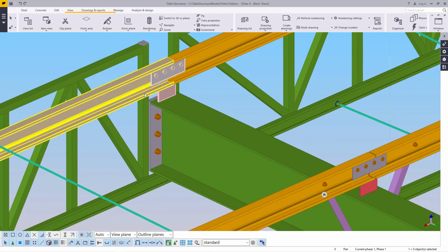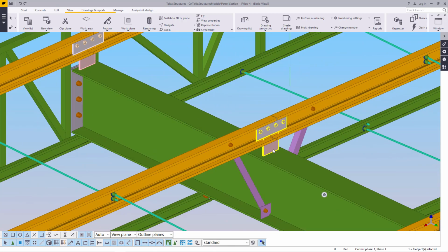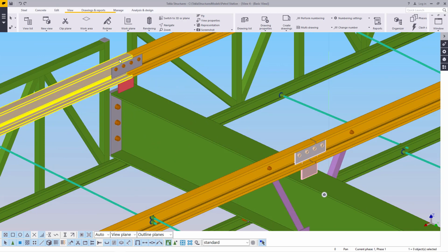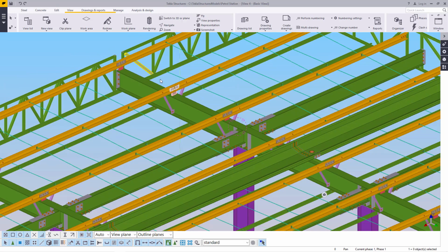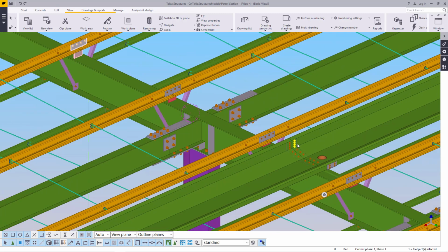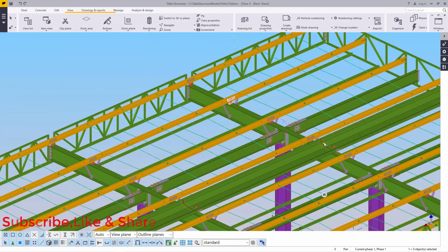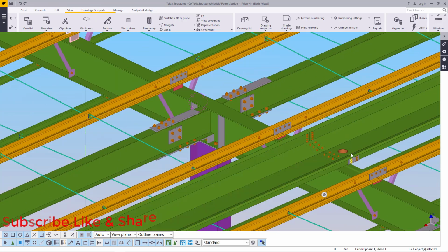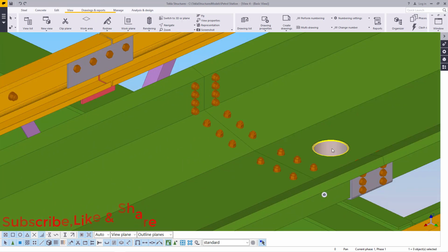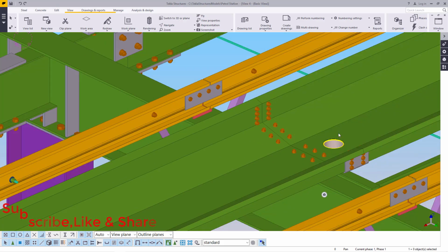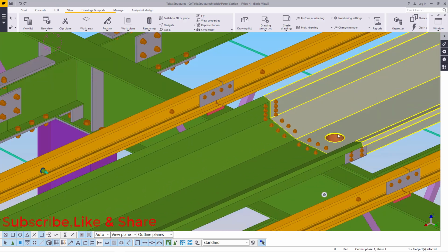So these cleats' heights are different, just to define or create a slope for our pilings, so that when we lay the sheets, the sheets will follow the slope, and water will be able to flow nicely, without any problem, to our valley-gutter here, and will be drained all the way to the ground or to the drainage system through these downspouts or down pipes here.